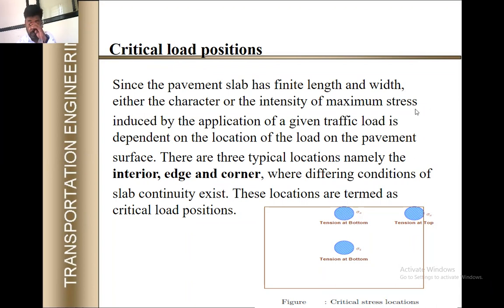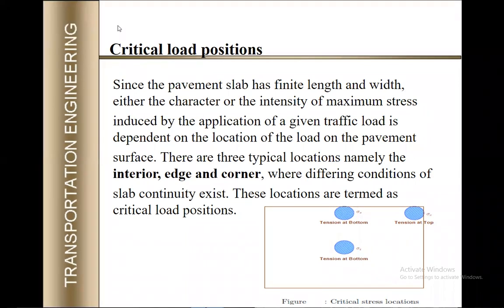What are the critical positions? You can see here, please. One is at the interior portion, another one is at the edge, and another one is at the corner. Please write down these critical load positions. Draw this figure.